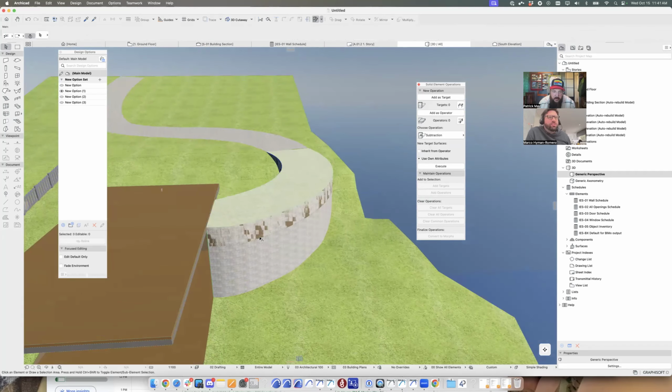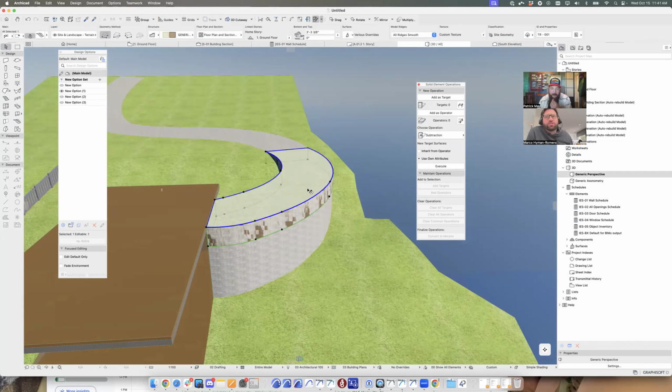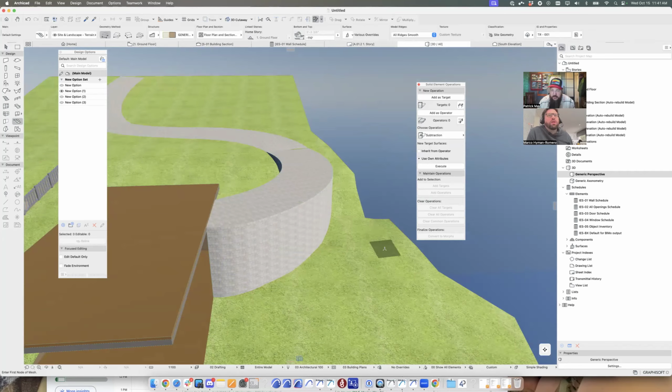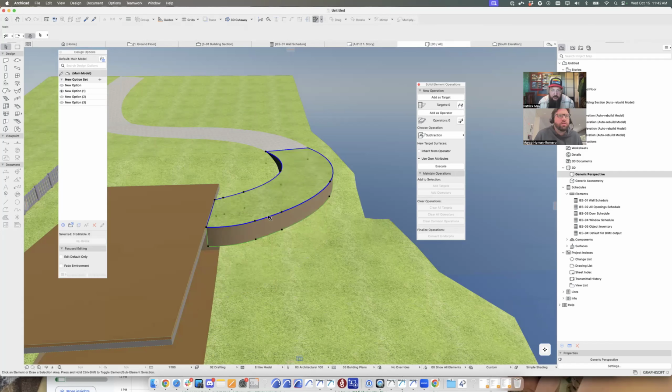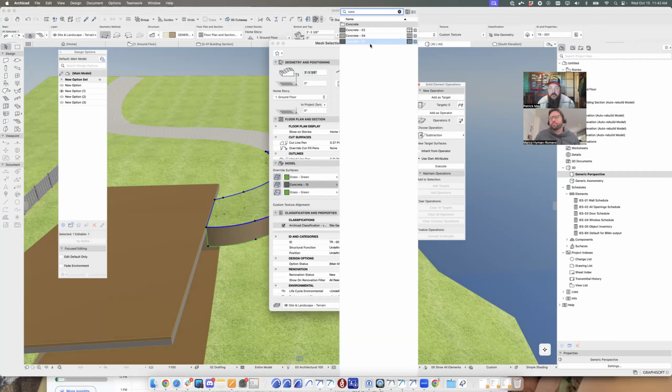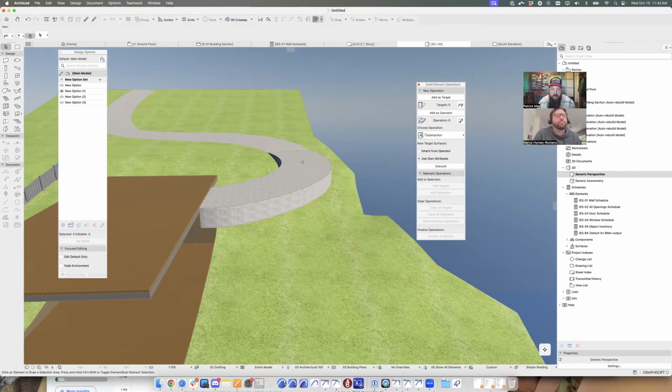How did you replace that slab with the mesh just now? All I did was drop this mesh to activate the mesh tool, and then I hold space and magic wand that slab. Now if I delete that slab, I have a mesh. I would have to come back in here and say that this is going to be that same concrete surface or whatever to match.